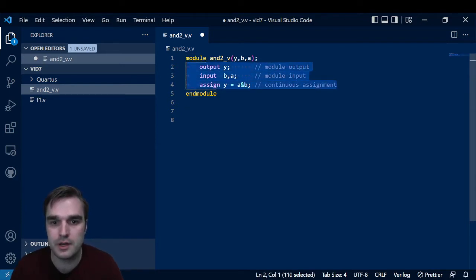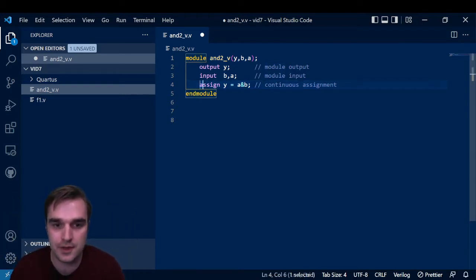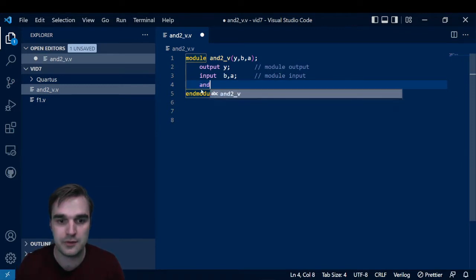Two things I want to comment here about this code. First of all, doing an AND gate, for example, is just such a common thing. It is so common that they already have an AND gate module defined for you as a built-in primitive in the language. So rather than us writing out this equation, I mean, it's perfectly fine to do this. An equivalent thing would be to use the AND gate primitive. And the way we would do that is we would say and